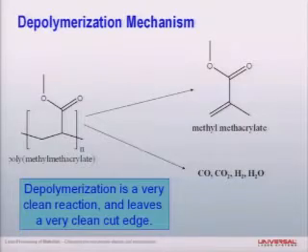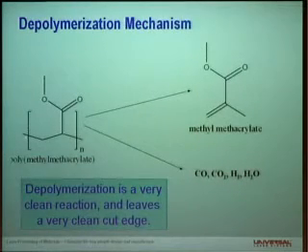So acrylic, I think, is one of the most useful materials for general construction, and certainly very amenable to laser processing. And one of the reasons that it is so amenable is the way it reacts with the laser beam. Acrylic is polymethyl methacrylate, so this is the methacrylate unit, and this convention, these brackets with the N, means that methacrylate unit is repeating over space 10,000, 20,000, 25,000 times for the very high molecular weight acrylics.